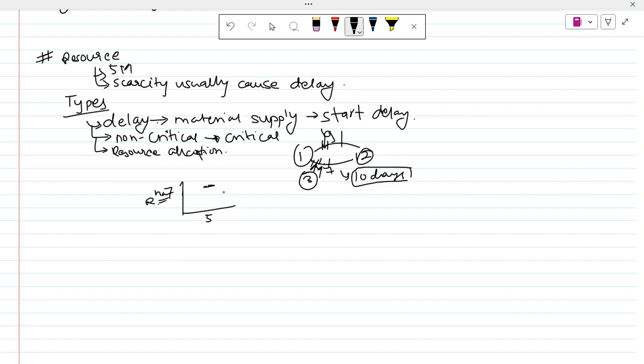Okay, I think you guys are perceiving this. This activity needs 3 men, this one needs 4 men, and this one needs 3 men. We only have 6 men on board. So we either keep the 4 men here and shift the 3 men there by 3 days.